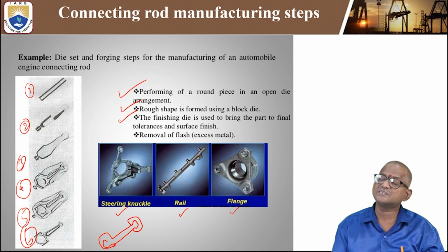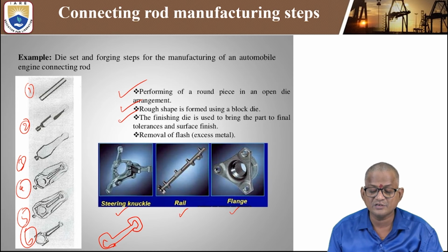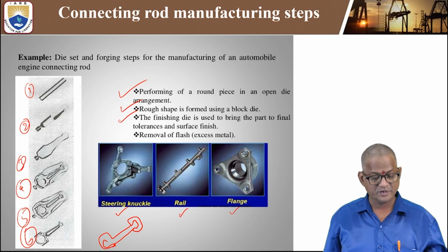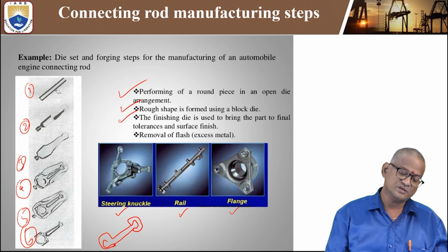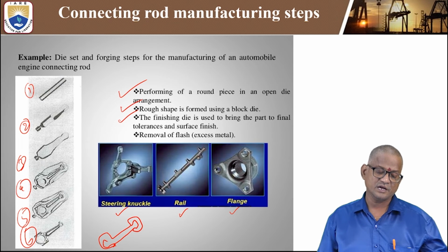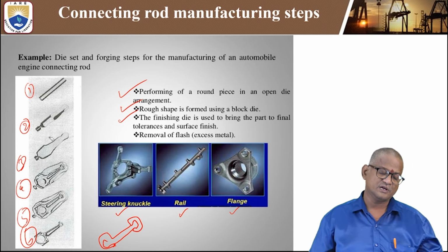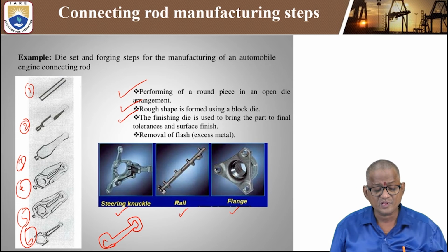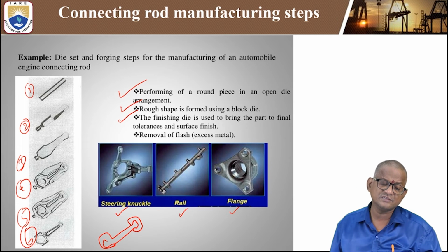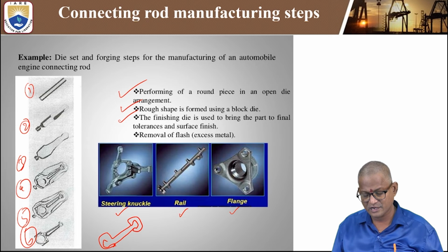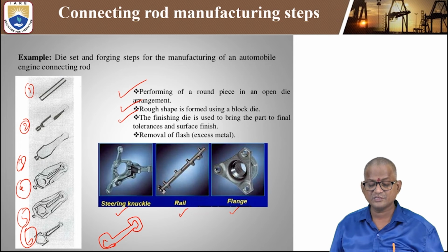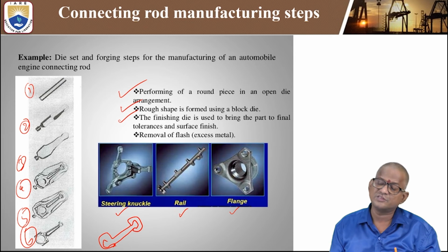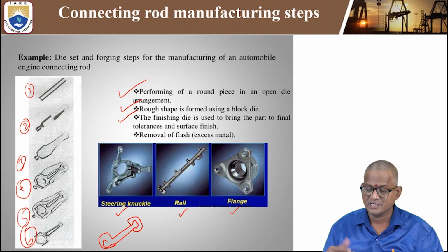There are basic six steps involved in doing the drop forging operations. Initially, first they will do the fullering operation, and at the end they are able to prepare the connecting rods, and once here the edging can be done, and after that edging at both ends can be performed, and also the final component can be obtained in the heated condition.